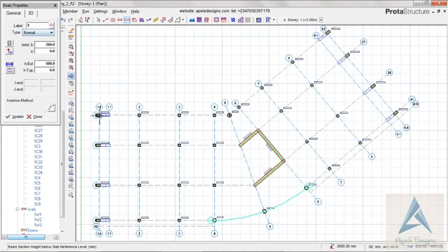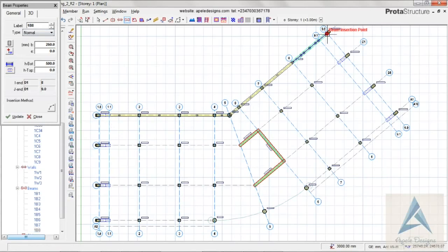Let's start creating our beams. To create continuous beam, you don't take it one at a time, like from 1 to 2, from 2 to 3. You have to take it from the very start point to the end. If we take it one at a time, Orion will treat it as separate beams. So we'll continue and lay it here. We'll escape to start another selection. We'll click, stop it here.